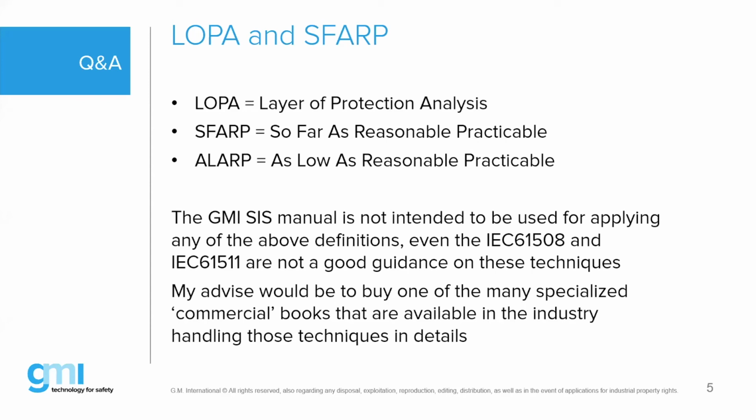Now, the first one, LOPA, Layers of Protection Analysis, and I mention it here in full words because some people may not know what LOPA means. Basically, you will investigate, and I know I don't have to move my hands too quickly on my virtual background, but those layers are layers on top of each other. And you will investigate how much protection your production unit at the bottom gets and how efficient those layers are.